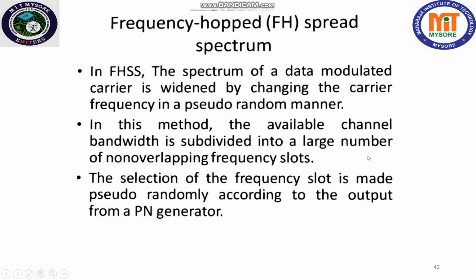First 100 kilohertz is fc0, 100 to 200 will be fc1, likewise fc2, fc3, fc4, fc5 up to fc9. You can have 10 different slots, and these frequencies can be randomly accessed by different bits using the particular circuitry designed for frequency hopping.